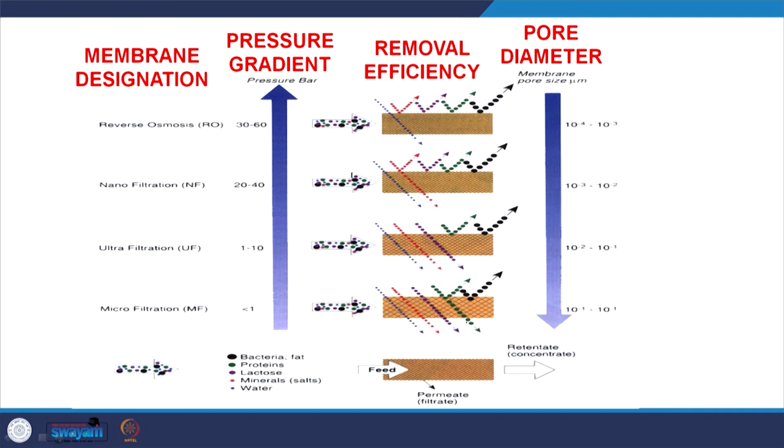But one aspect is, as the membrane pore size decreases, right, or let us say pore size here is highest, right. As the membrane pore size decreases, the pressure required will increase considerably, right, and then the money and such too, right. The cost for reverse osmosis are due to two factors. One is the pressure, and also because of changing the RO membrane from time to time.